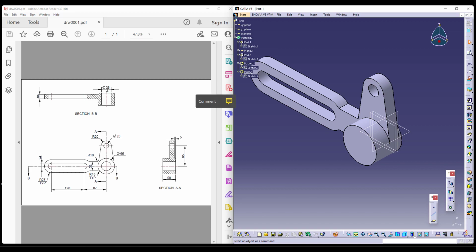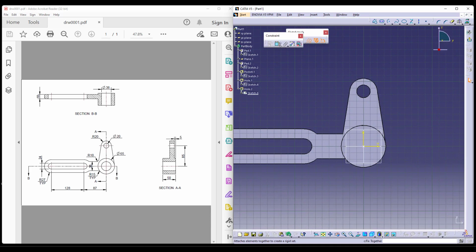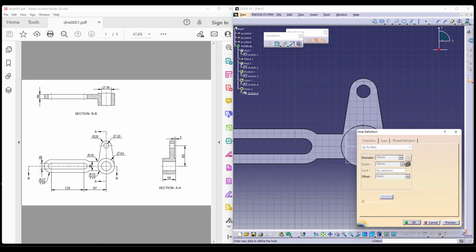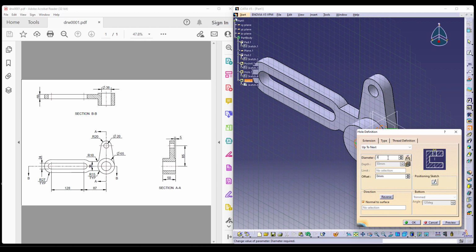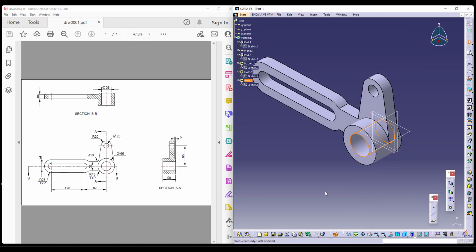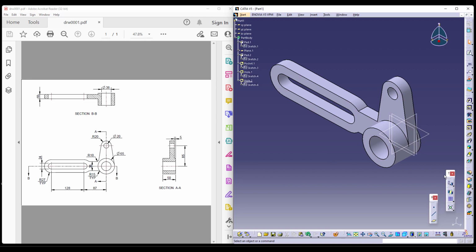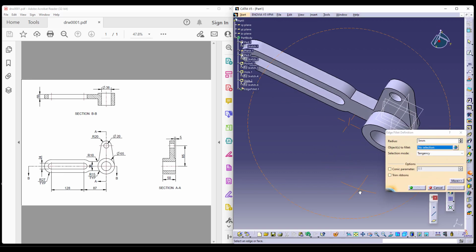Now the center hole is 38, which you can see is again through. I'm taking the center and giving concentricity, then maintaining 38. Drills the feature. Last but not the least, we do have rounds as well as usual.